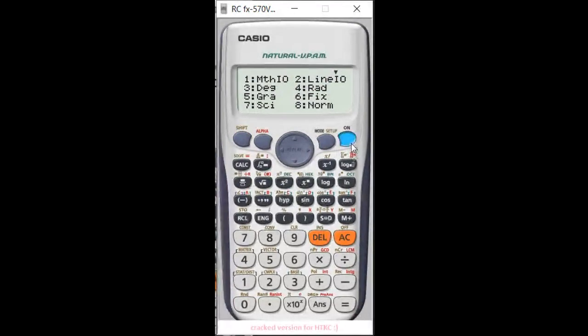I did recommend you get this Casio. It's of utmost importance. Just go to mode, equation 1. Over here we just put in the coefficients as is. A will be the coefficient of I1, B the coefficient of I2, and C will be the voltage. So what is I1 over here? 27. Yes. Oh, my bad, I pressed something else. Okay, 27, then the 12, and the voltage is 30.